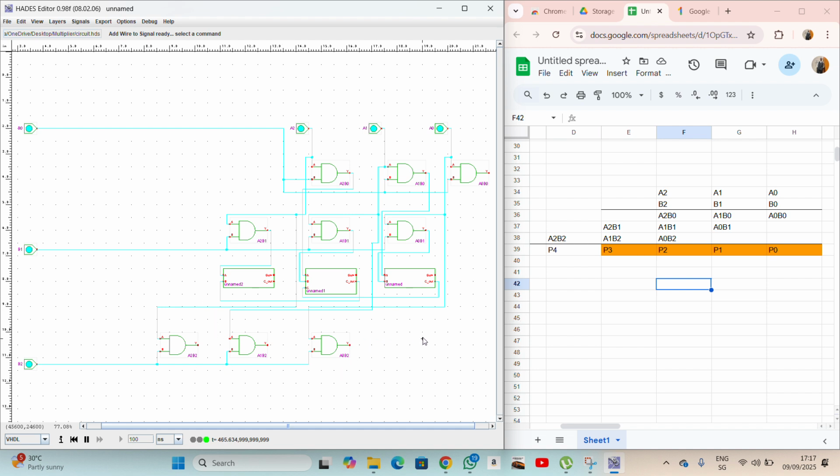I need to do the final round of addition. Now what do you realize? You realize that over here we don't have any other thing to add in this column. So in this column we have the addition of the sum that we had in this point and the new variable that has been created here. So that's why the only two that we're adding. So we need a half adder. So I'll copy this and then I'll put it here.